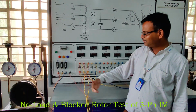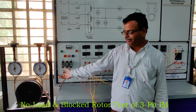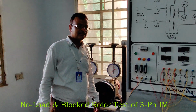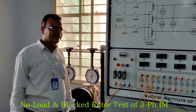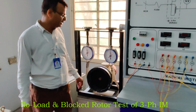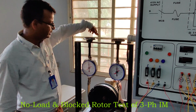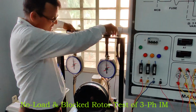Wait for the stopping time of this motor, and then we will perform the second part of this experiment, the block rotor test. Block rotor test means the rotor is blocked. Rotor is blocked means it will not rotate. You have to tie it with the help of this pulley. Then how to block it? With the help of this mechanical load, tighten the belt.